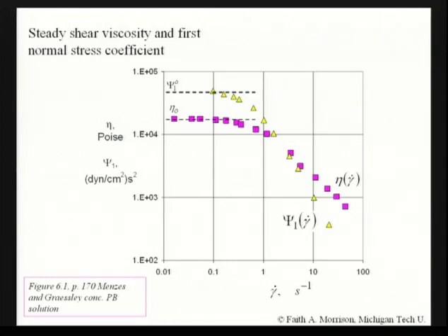Now, you've seen this slide before, and let's look at it more closely. It is a slide that says that the viscosity varies with shear rate. And now I'll point out a subtlety of this graph. Notice how this is labeled. It's not labeled gamma dot naught. And that's because of what we just discussed. It's labeled in terms of the magnitude of the rate of deformation tensor.